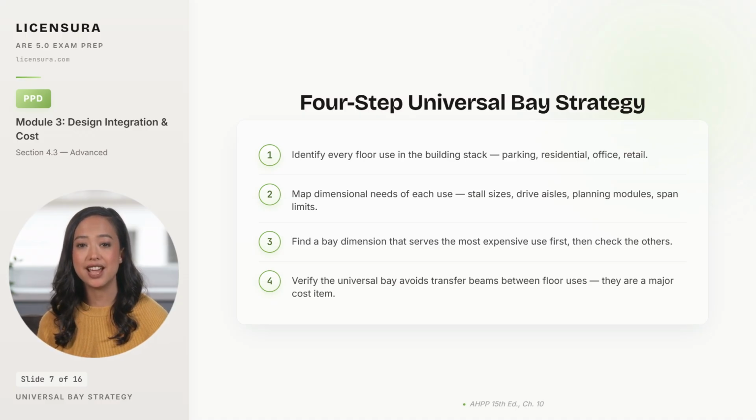plus residential stacks. Fourth, verify that the universal bay avoids transfer beams between floor uses. Transfer beams between parking and the floors above are a major cost item, and the whole point of the universal bay strategy is to eliminate them. Done right, the universal bay can save the project significant cost on the structural package.